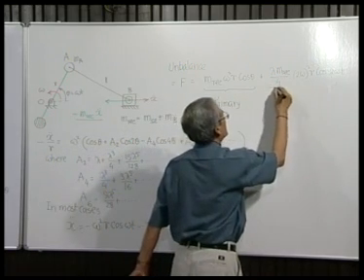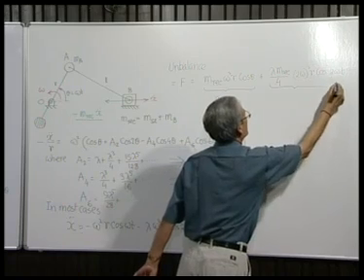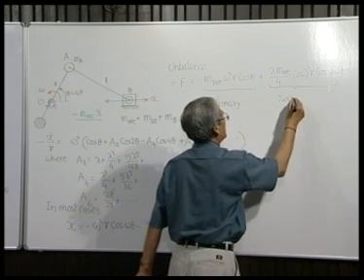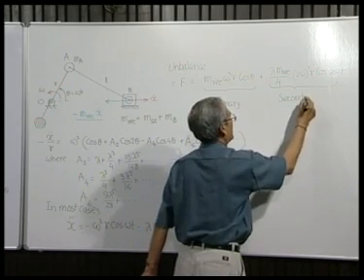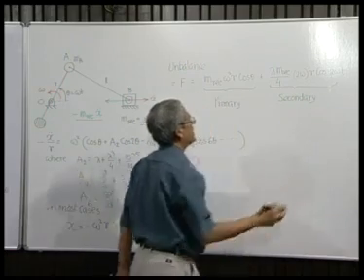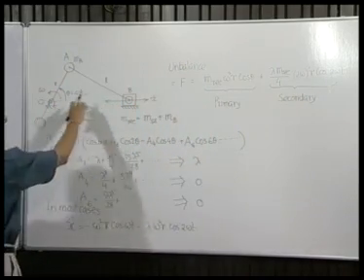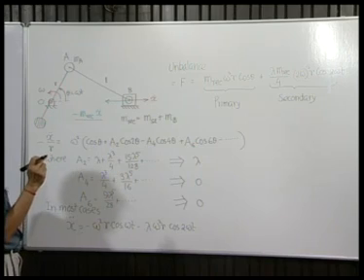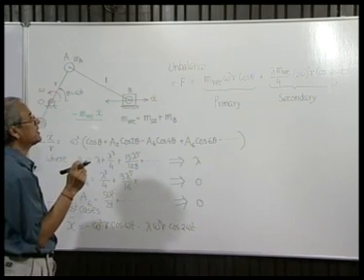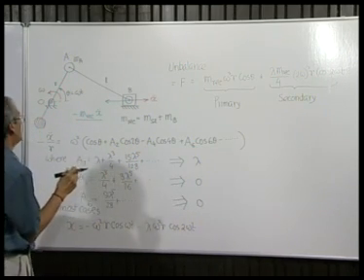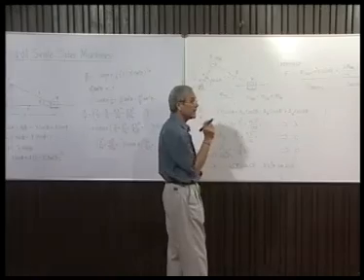This force, which is the second harmonic, we call the secondary, again can be considered as the component along x of that centrifugal force when a mass of m reciprocating into lambda by 4 is placed at the tip of the secondary crank.